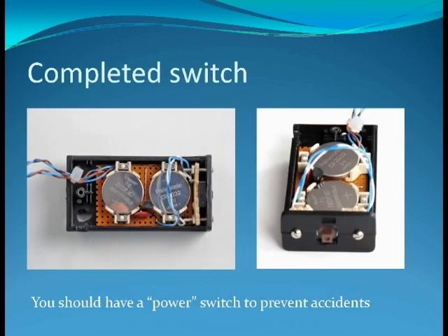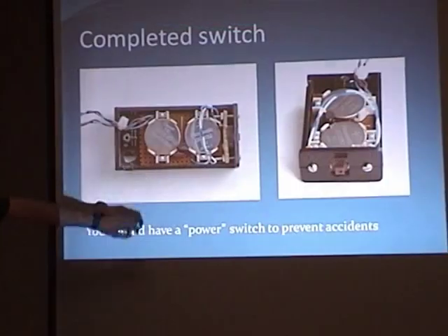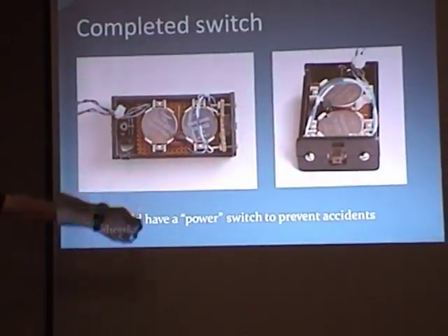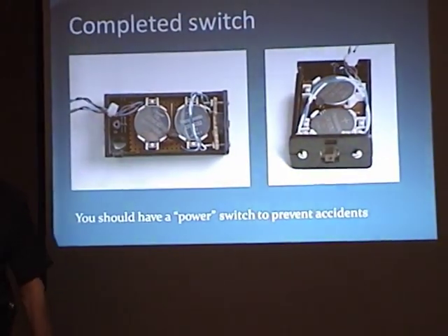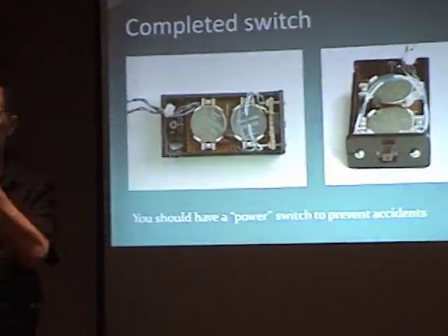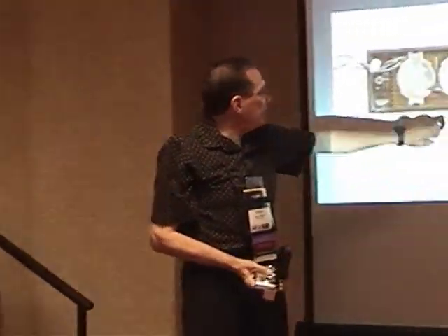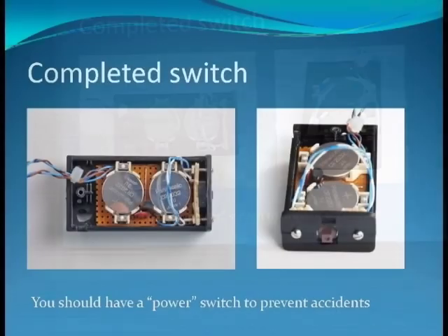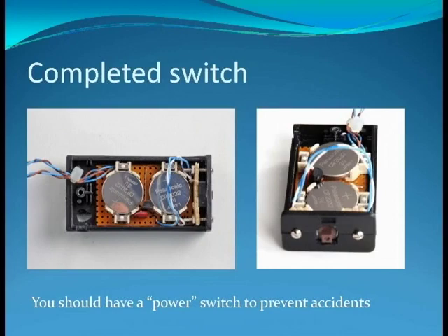This is the completed switch box on my camera that I've been running around shooting with. And you can see from the insides how simple the wiring on it really is. I wanted 6 volts, so I've got 2 of these little lithium coin cell holders in there. This little black thing is the voltage regulator. And everybody please bear in mind, we're talking about this little box right here. This is small. A switch that I mounted very simply by a little piece of perf board in one end. And it's a very effective way of doing this. It works as good as if you spend a lot of money on it.